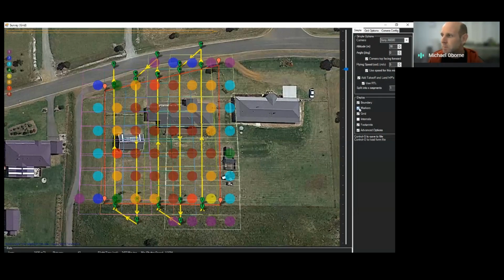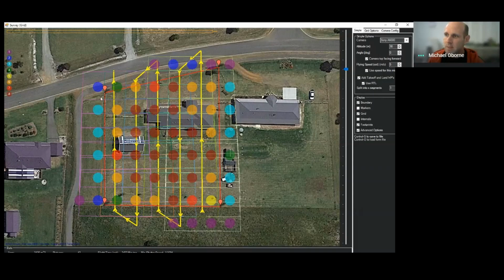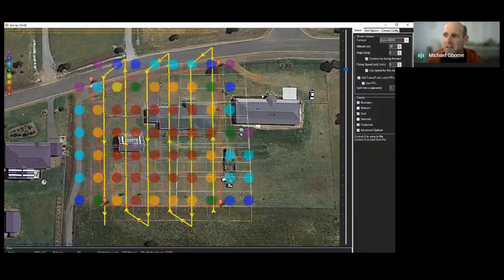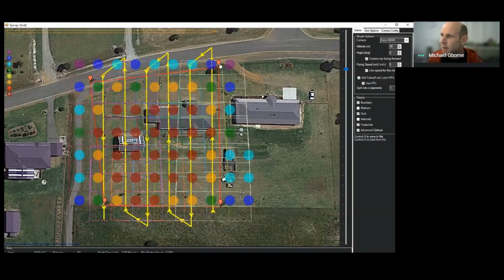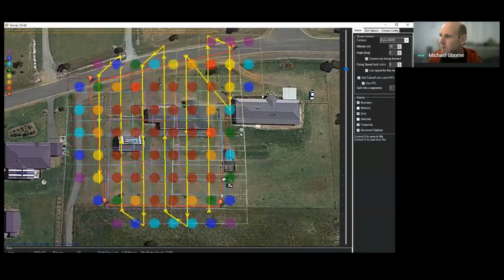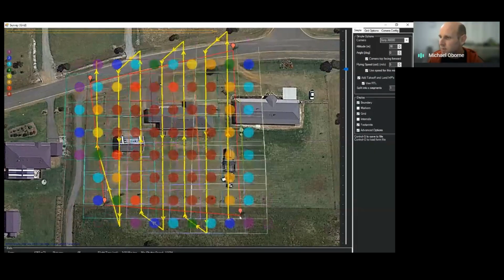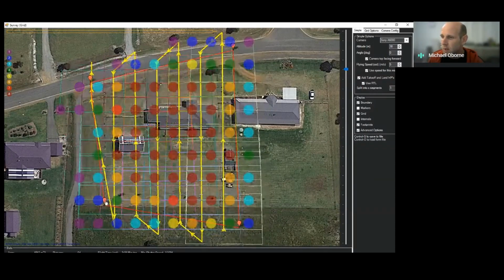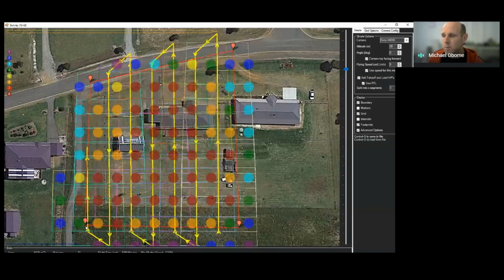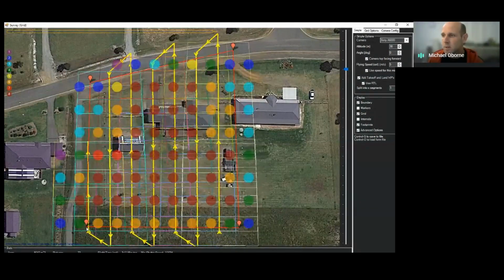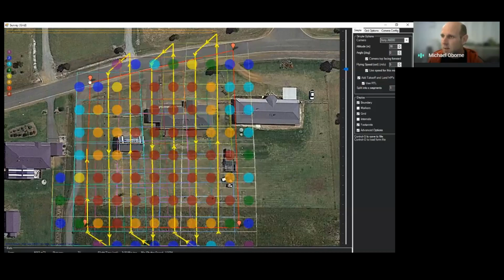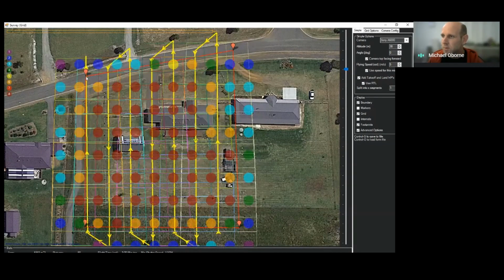One thing you can do is I'll just turn off the markers again, and you can actually drag the polygon points. If I go over the side edge of the polygon, I can actually drag this point further out. Because I want better coverage, I'm going to do that on every side, just so that I get some nice red dots right into the center as well. For photogrammetry, obviously you want a lot of overlap on the area you actually want. So I'm just going to drag this, and maybe I'll move that one over there a bit more as well. So maybe, there we go.